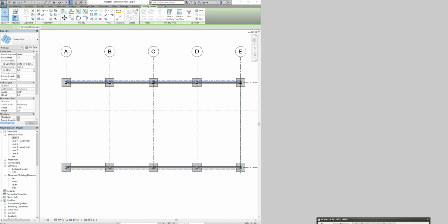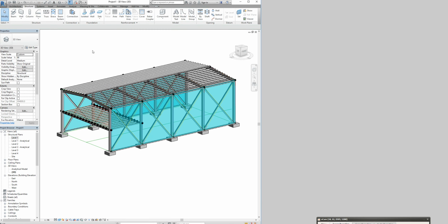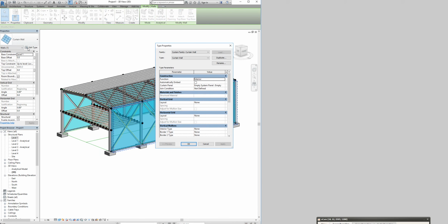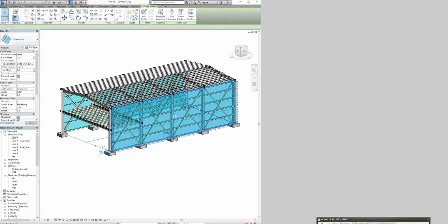Next slide. So it just shows me how the building should look like. So not quite, we're missing something here. Let's check in edit type, the configuration here, type properties. So we got exterior, none. Oh, I was missing this step here. So look here, fixed distance. So we just have to put here fixed distance. And here 1200. Adjust, apply. Now it's looking good.